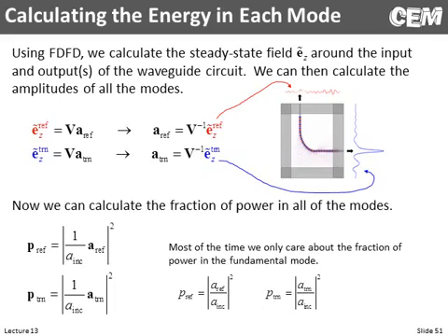it's the same concept. So if we go in these arrays and we pull off the one amplitude for both of these that corresponds to the zero order mode, or that fundamental mode, now we can use these equations to calculate the power in that fundamental mode that's reflected and transmitted through the guide.